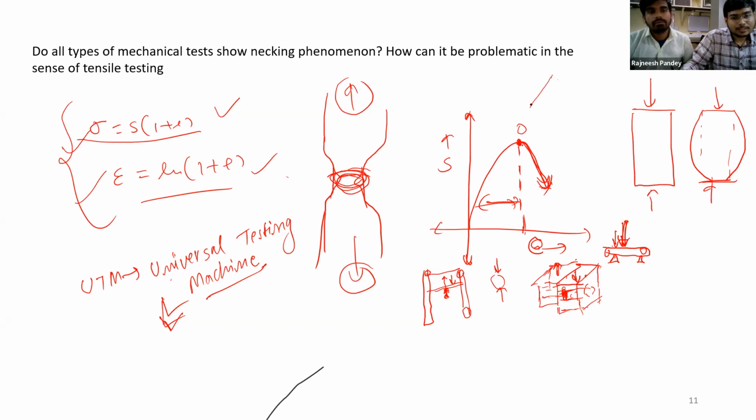If you are talking about shear strain, it is based on the torsion test. The torsion test is done on a separate tester where we can generate only a pure shear case, and we rotate that sample, like you twist clothes after washing. In a similar manner, a torsion is applied on the specimen. That is a different testing machine we use for that. That test gives us the twist in terms of angle, and that is converted to the shear strain.